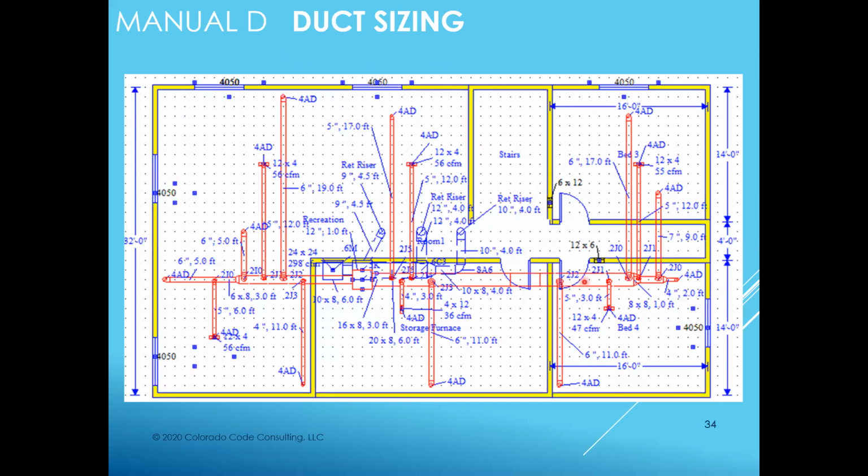So what this means is that this one has 2 takeoffs downstream. This one has 1 takeoff downstream, and this one doesn't have any. And this is why trunk reductions, like the one you see here, are so important, because it repressurizes this section of ductwork.